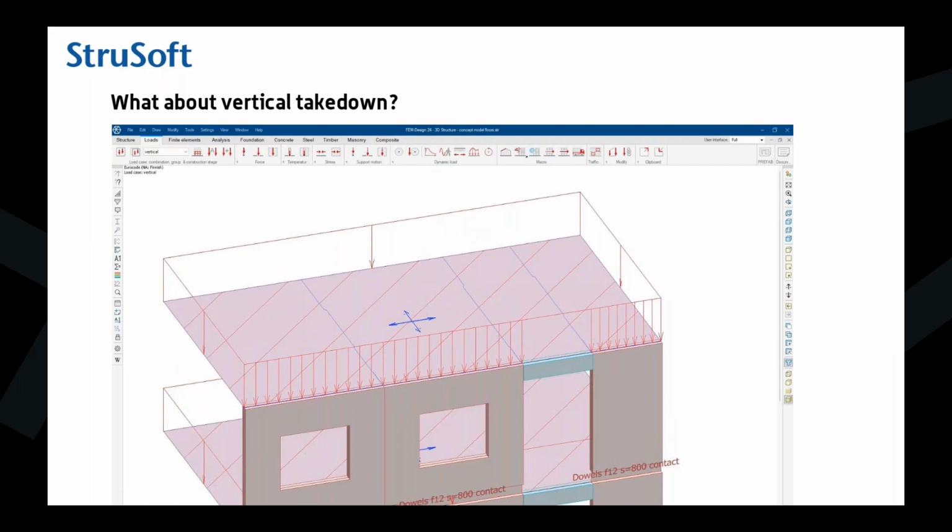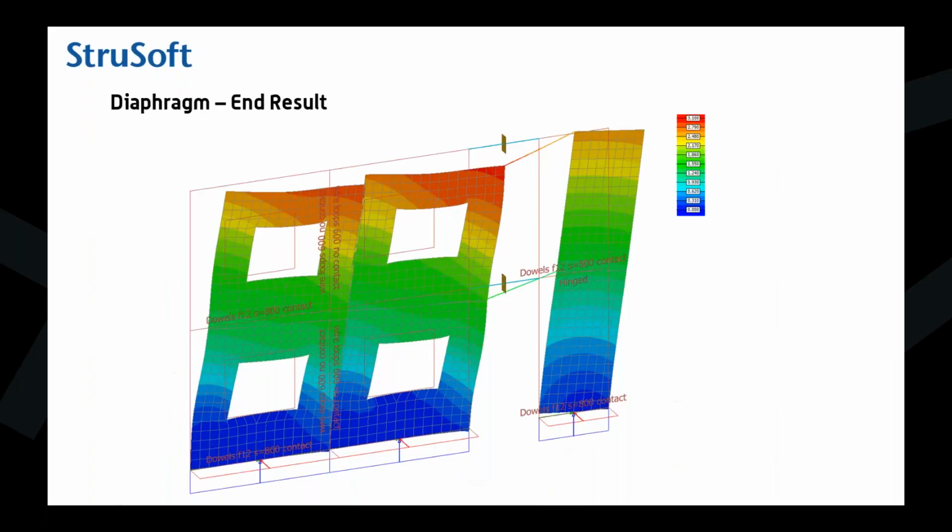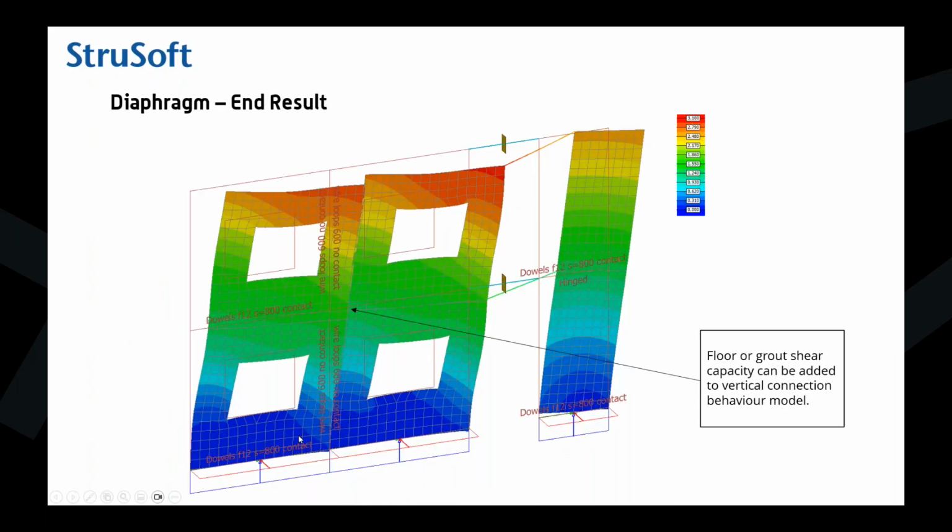It's just a cover where you can define which are the load bearing members. So you always select walls underneath the cover to take the load, and then you can select the loading method or load transfer method and the load bearing members, and then you can use surface loads in your buildings.